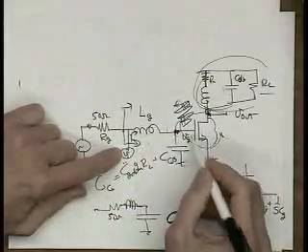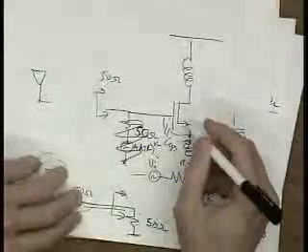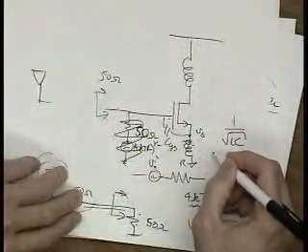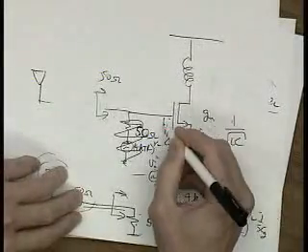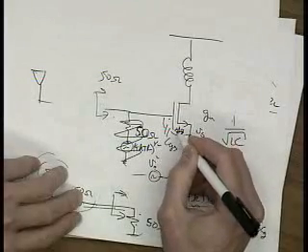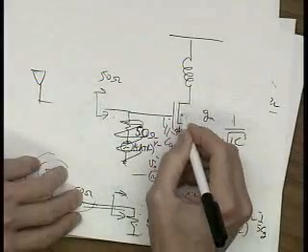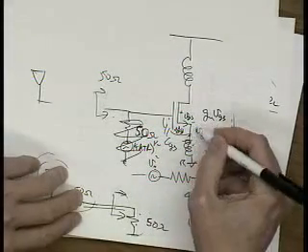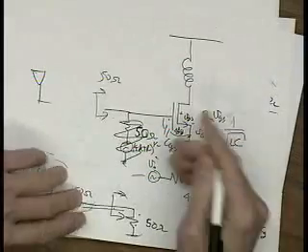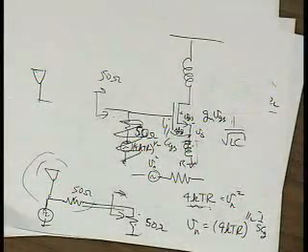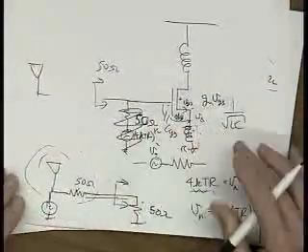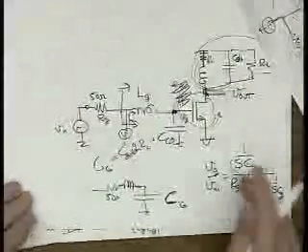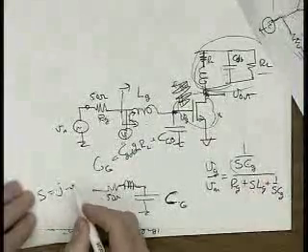In your problem you'll have an inductor down here, right? So you have to worry about the fact that V source isn't 0. It's gm times VGS, since there's a VGS across here. So gm times VGS is the current, and you just have to solve that through, just like we always did before. So the problem in your homework is no different from what we did before, it just has impedances now, and after you calculate these things, let s equal j omega, and you can begin to see what happens.